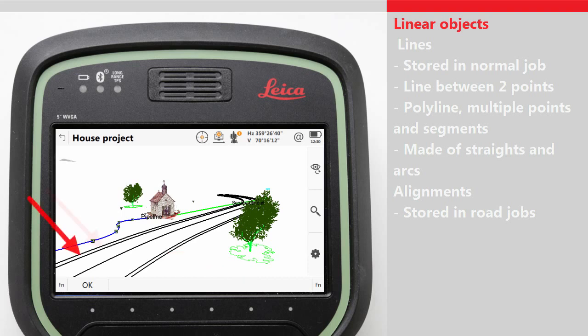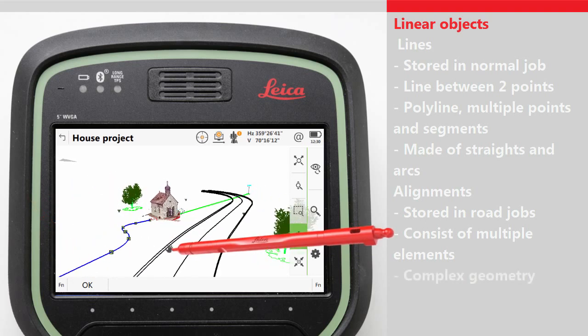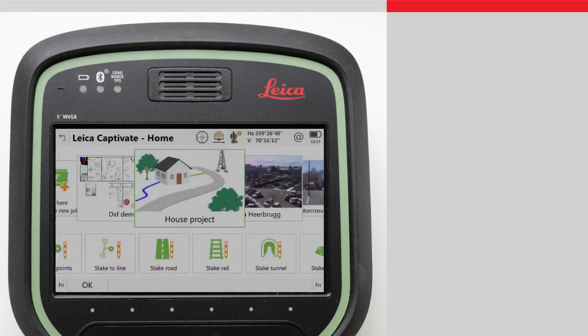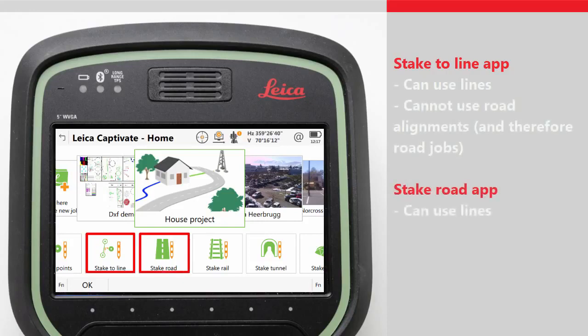Typically, road alignments consist of multiple elements which define the road and can include relatively complex geometry, such as clothoids and spirals, and also normally consist of separate horizontal and vertical designs. In this road job, we can see the alignment of a simple road, which includes the centre line, edge of road, and drain. Now we know a little bit more about lines and alignments, we now need to know which of these objects can be used in which apps. Basically, the stake line app can only use lines and cannot use alignments, whereas the stake road app can use lines and also alignments from a road job.